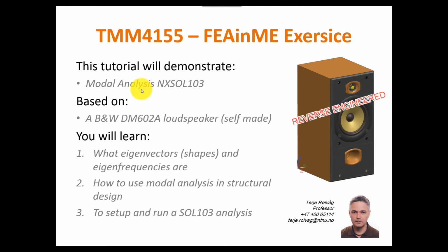In this video, I will show you how you can use eigenvectors, mode shapes, in order to improve the structural design of the loudspeaker, and how you can check the eigenfrequencies and compare them with certain excitation frequencies in order to optimize the structural design. And of course, I will show you how to set up and run this analysis.